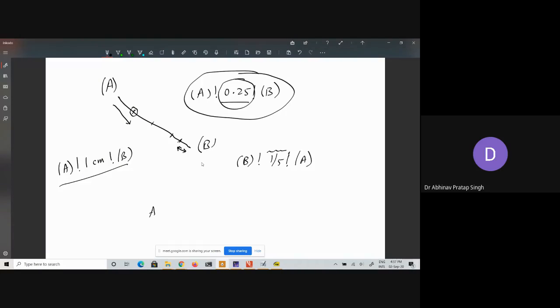What I will say is A, exclamation mark, C, exclamation mark, B. What this does is, let us say you have some line from point A to point B, and there is some other point C. It drops a perpendicular from C to this line, and it gives you this particular coordinate. So this can be very helpful for you to drop perpendiculars.